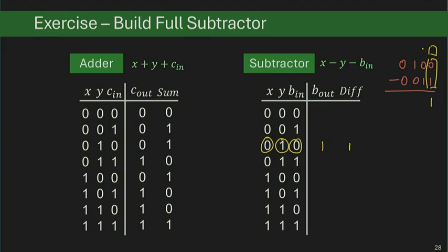Can you use XOR? Yeah, you can also use XOR gate for the difference, I suppose. Yeah, but I have to see the full table to really try to verify that pattern. Oh, I see. Yeah. So the implementation depends on all the rows of the truth table. So we really have to fill it out entirely to see if we can build it with a single gate or with multiple gates, which gates and how they are composed.